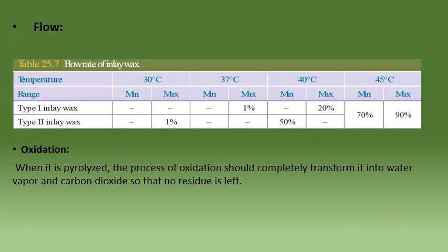So yeah, always make sure whenever you are using a wax, there are some criteria for its flow rate. This table column is very important. Try to memorize this, and always make sure after you do the burnout, do the casting as early as possible. Do not leave it for longer time, because the more the time between your burnout and casting, more will be the distortion. So in order to reduce your residual stress and distortion, it's better you do the casting as early as possible. If supposing there is any delay, you have to make sure you store it in appropriate temperatures.